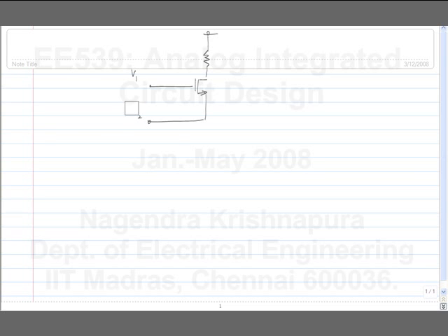So to drive the very low impedance input, we will use a buffer. The input of the buffer is assumed to have high impedance, so that again V2 also sees a high impedance input. So this should work for us. Now the only voltage buffer that we know of is the common drain amplifier. So we are going to use that.